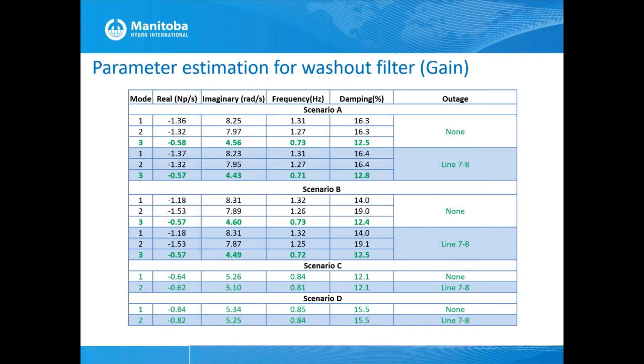But today, there are more sophisticated power system stabilizers, especially for interarea modes. You can do global measurements or wide area measurements, and provide feedback. But there you have to be careful with signal delays, and how they can impact performance. But since the oscillation frequencies are very small, and today communication is very fast, you can use them. And I have seen a few instances where they use global signals for interarea oscillation damping.